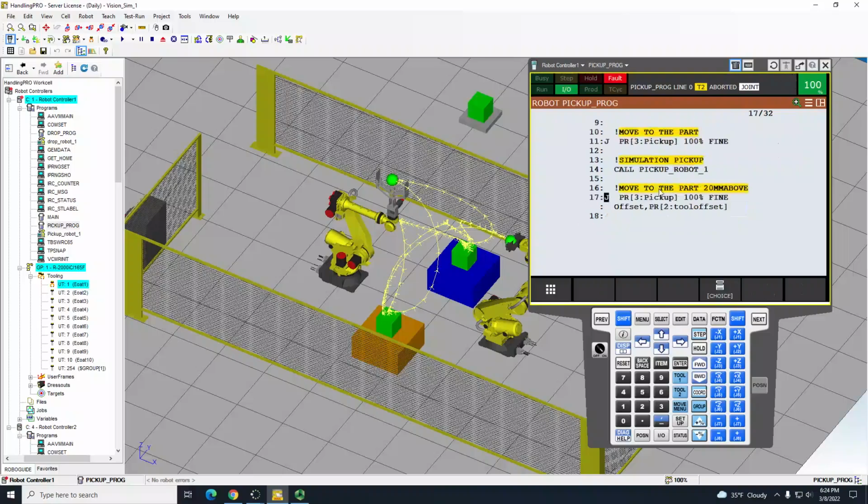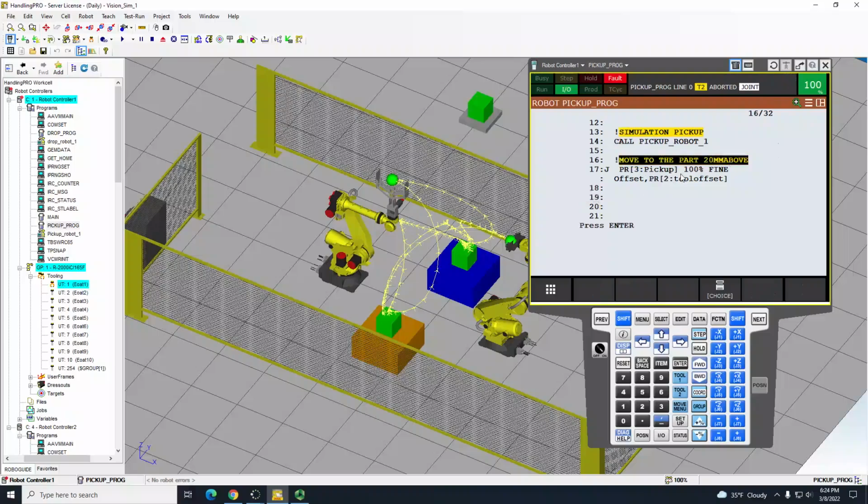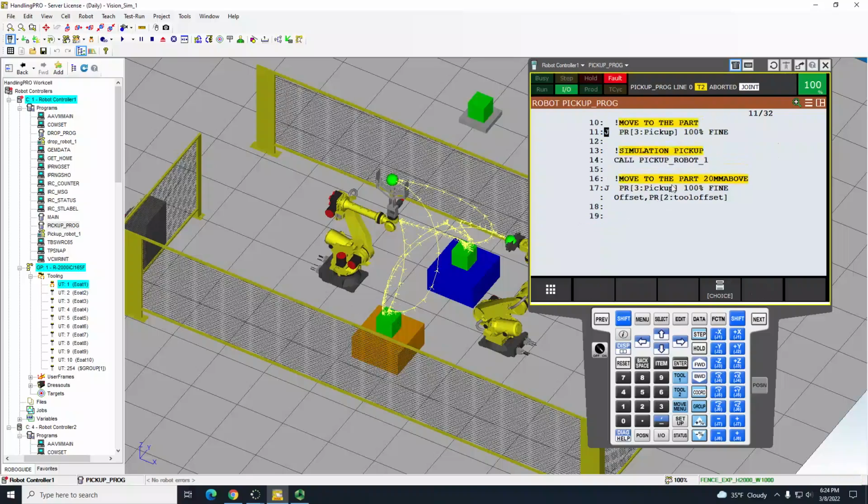So now the DO is engaged. It's like the pickup simulation is on. I mean, the part is on the robot's end effector, or end of arm tooling. A lot of different synonyms for that term. Anyways, it moves further. After picking it up, there is a tool offset of 20 mm above. Like I told you guys, I just want to move the tool right above my part. That is the reason I've given it as tool offset.